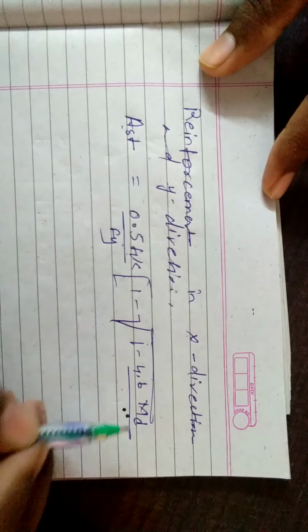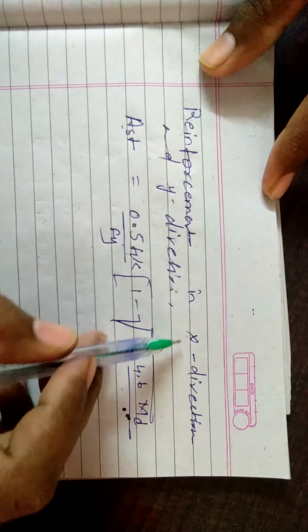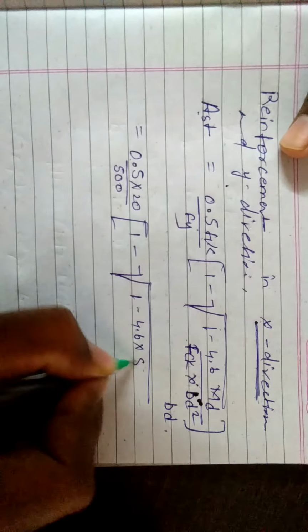Here we will take the value of bending moment with respect to X and with respect to Y. Not the greater value, as per the direction mentioned. MD is equal to that value, and FCK into BD square, in bracket B into D. After that we will put the value: 0.5 into 20 into Fy, which is 500, in bracket 1 minus root 1 minus 4.6 into